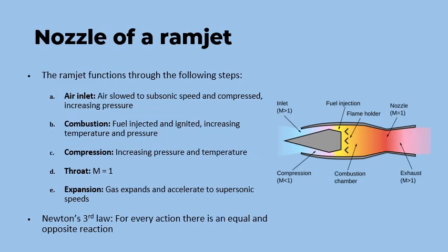The most important part of a ramjet is its converging-diverging nozzle. For our investigation, we will focus on understanding and modeling this component of the ramjet. A converging-diverging nozzle has three main components: the converging intake, the throat, and the diverging section. Functionally, it is similar to a Brayton cycle engine, such as a turbojet, where it at first compresses the working fluid, injects fuel, and then facilitates an expansion that accelerates the working fluid.